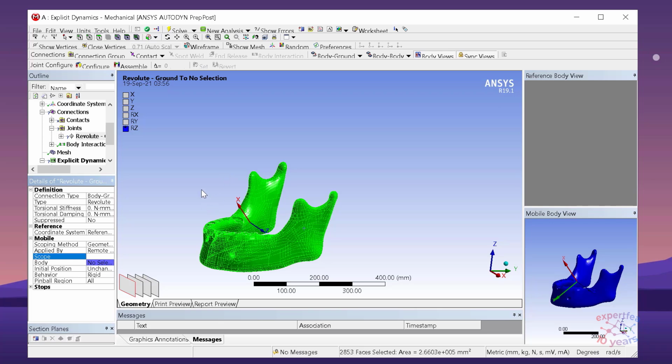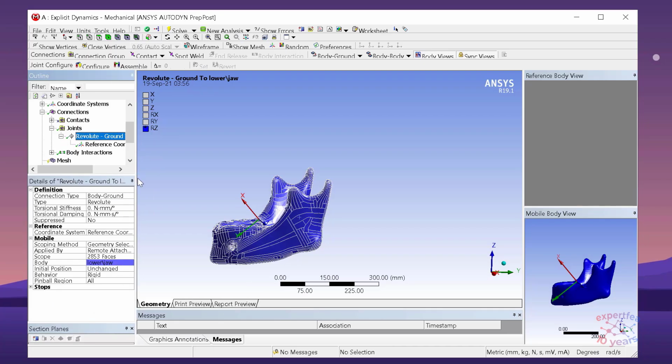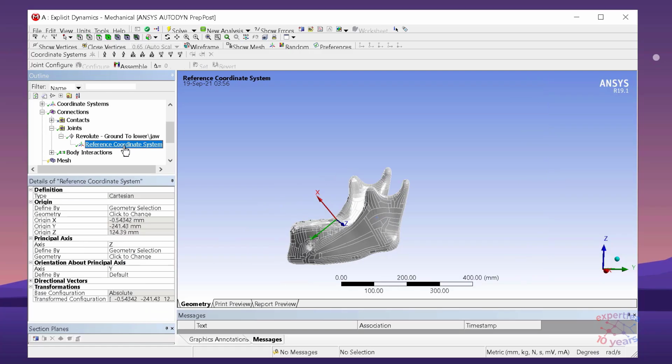I like the position of the Z axis, but of course we will need to move the coordinate system here to be here. Alright, so this joint received the coordinate system, and we would like to move it. Can we move it like this? Let's see, offset Y. On the Y-axis we'll go with, I don't know, maybe 150 millimeter.